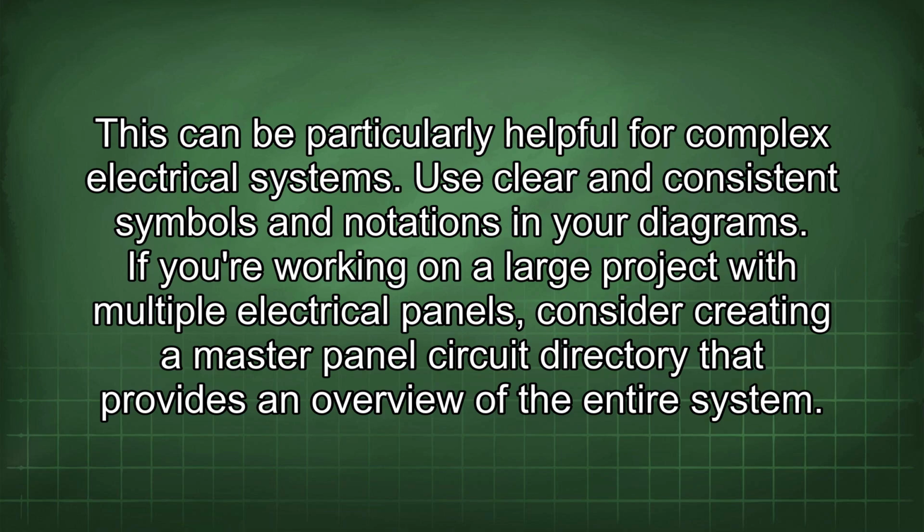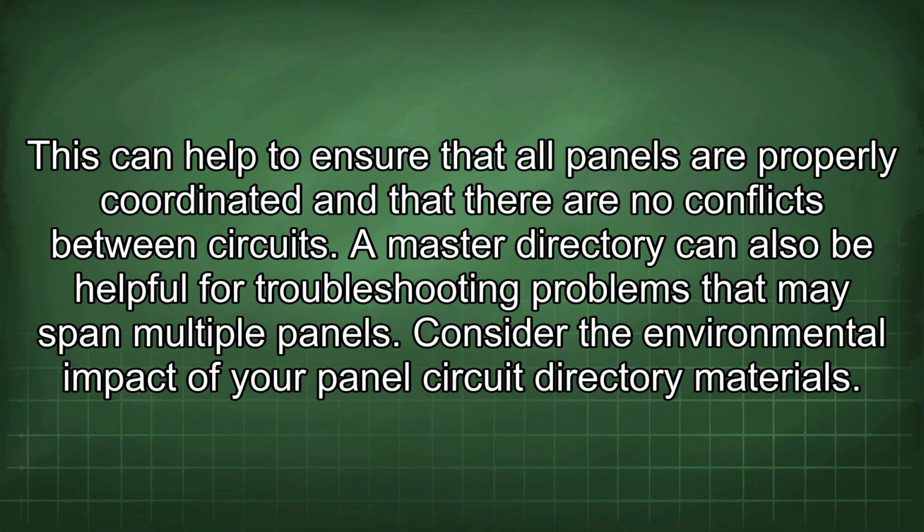If you're working on a large project with multiple electrical panels, consider creating a master panel circuit directory that provides an overview of the entire system. This can help to ensure that all panels are properly coordinated and that there are no conflicts between circuits. A master directory can also be helpful for troubleshooting problems that may span multiple panels.